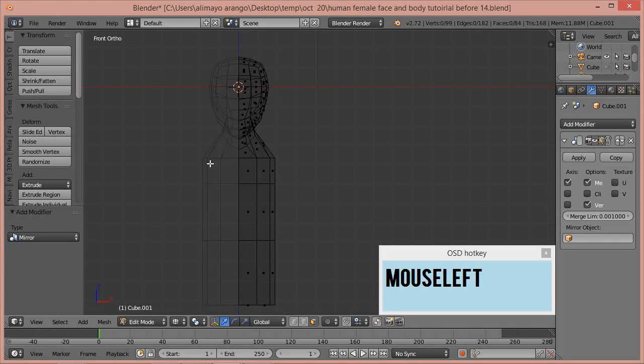So with this mirror modifier on here, what you want to do is go to the mirror modifier options. You want to click right here. This is clipping. This option will make sure that the model won't pull apart away from itself. Then you can click this little triangular looking button right here, and this just makes it look like the virtual half of the modifier is actually fully on the model. I like it like that, and it seems easier to work with this option on for me.